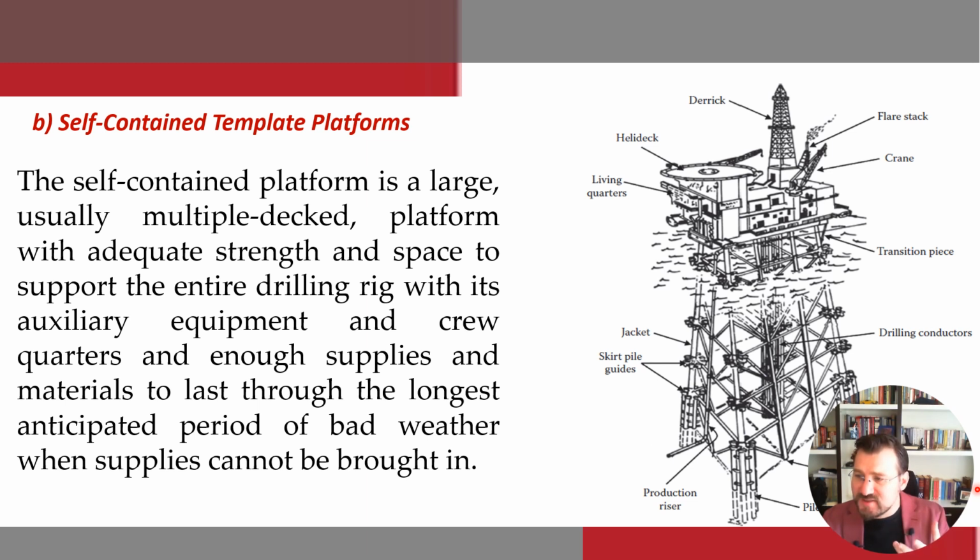The term template is derived from the function of these structures actually to serve as a guide for the piles. So the piles, after being driven, are cut off above the templates and the deck is placed on top of the piles. So the template is prevented from settling by being welded to the pile tops with a series of rings and gussets. Hence the template carries no load from the deck but merely hangs from the top of the piles and provides lateral support to them.